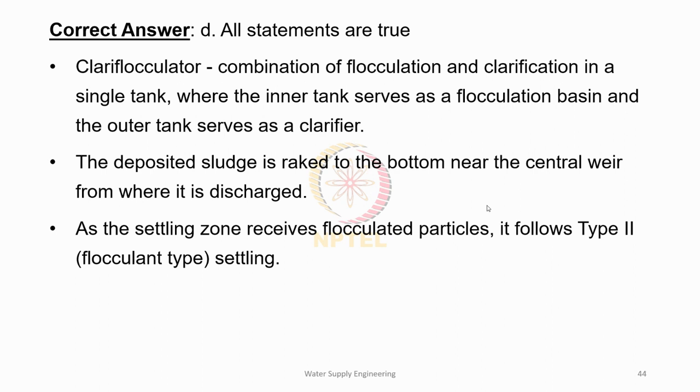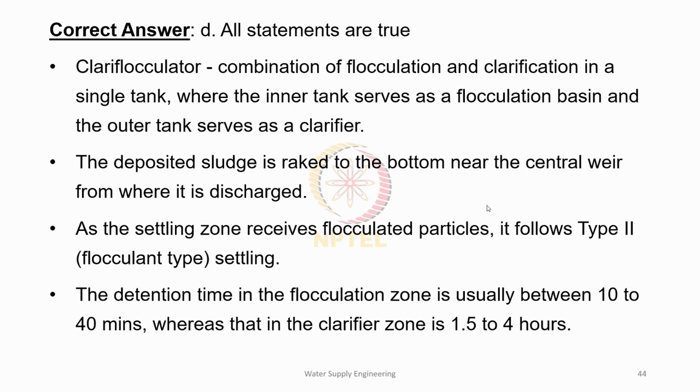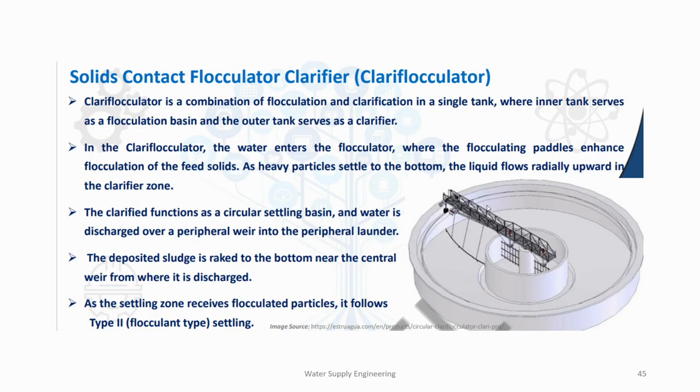Since the settling zone receives flocculated particles, it will follow type 2 settling, that is flocculant type settling, because the particles are already flocculated. The detention time in the inner flocculation zone is 10 to 40 minutes and in the outer clarifier is 1.5 to 4 hours.